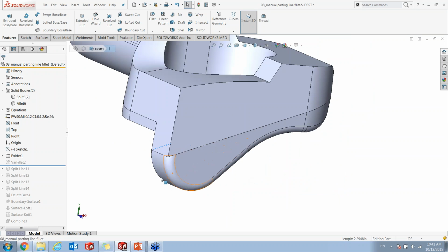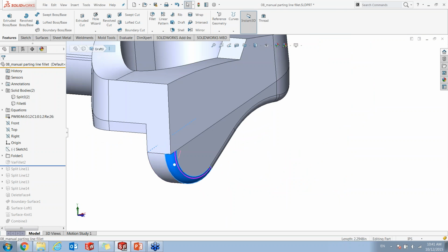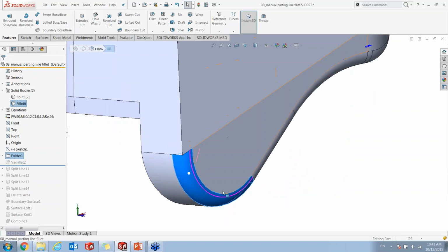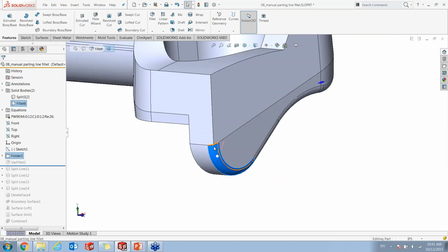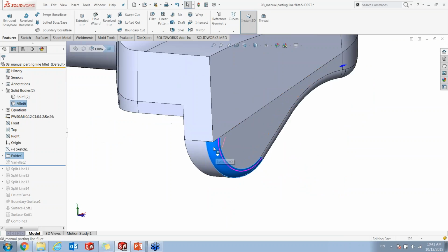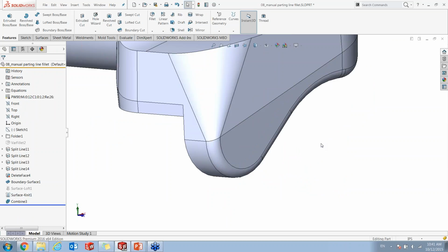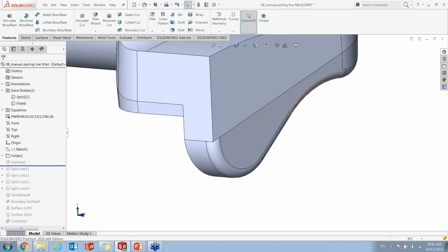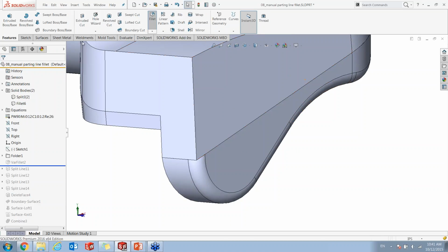Okay, so now for the bottom body, I have actually created a fillet in blue. And now I'm going to create another fillet that connects with exactly the same size as this fillet, but it is variable size, because we want a result like this. It is connected to the bottom fillet, and then it becomes larger and larger. So you may say that, oh, we can directly use a variable size fillet. Okay, let's see how it works.